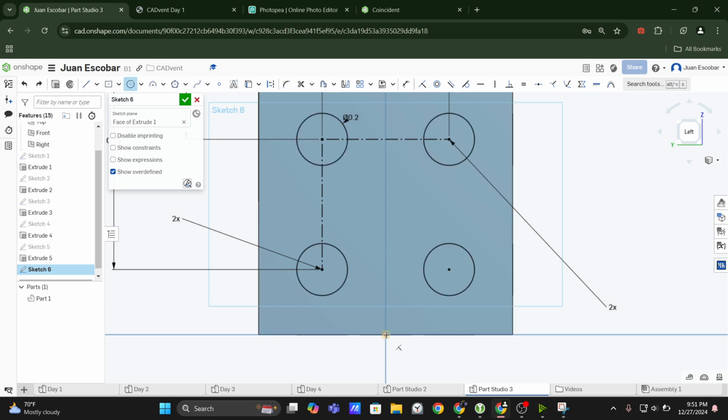I'm going to start with the origin, hover over the origin, see that coincident icon, and move vertically. Now I'm going to hover over the midpoint, move horizontally, and now we have that horizontal. See the orange dotted lines, and now if I hover over here, you can see both the vertical and the horizontal lines. It is both vertical from the origin and horizontal from the midpoint.